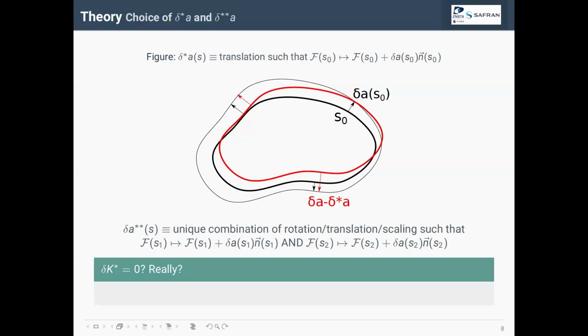But now you should be a little bit suspicious. Does this transformation really incur no change in the stress intensity factors? Well, no, in general. It's only zero if you have uniform stress or remote loading. So from the point of view of the crack, all the loading is uniform. But it's not really fun if the loading is uniform, right? We want to be able to handle local residual deformations that cause residual stresses or stuff like that.